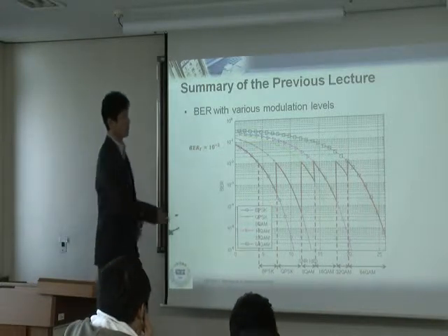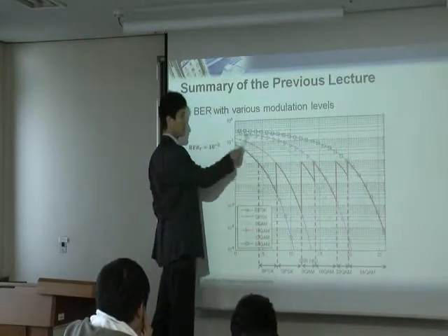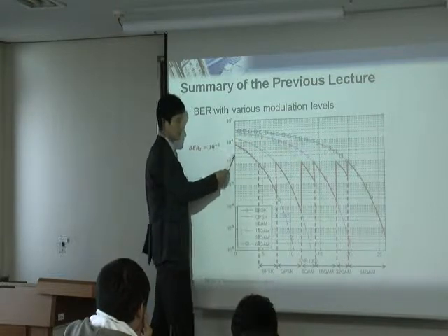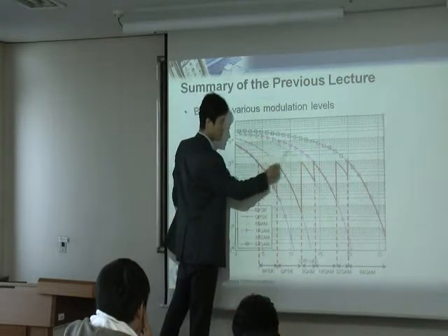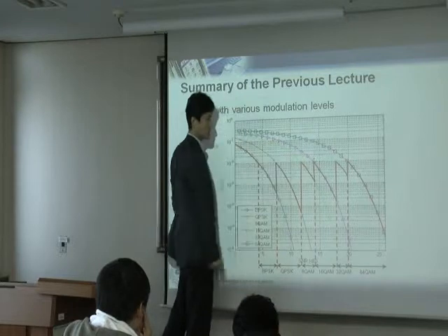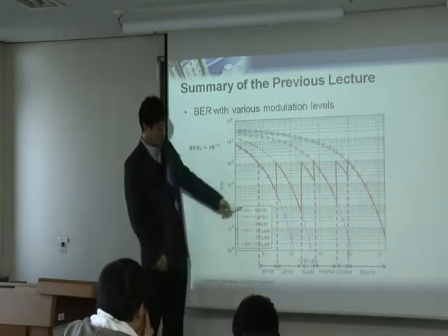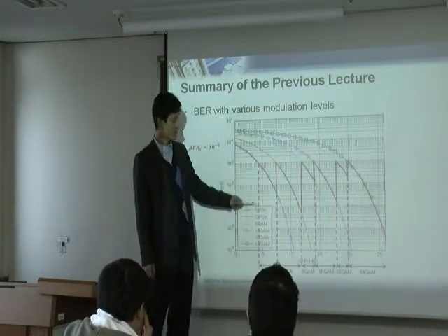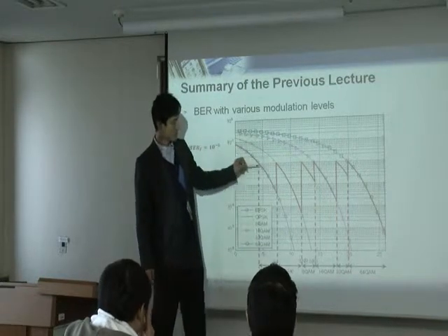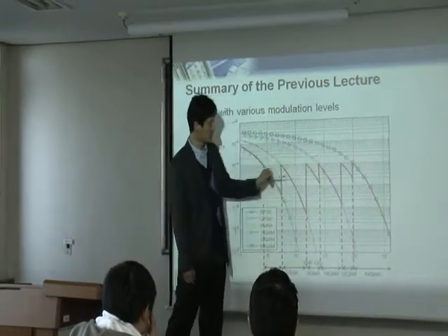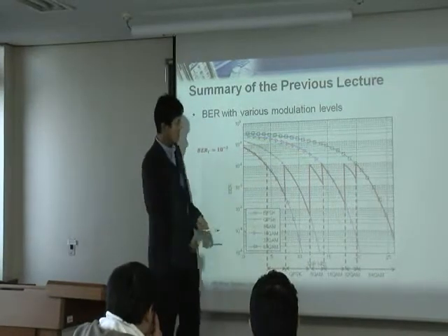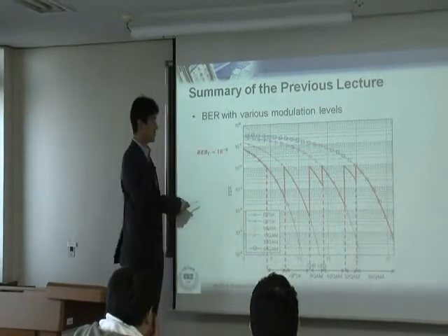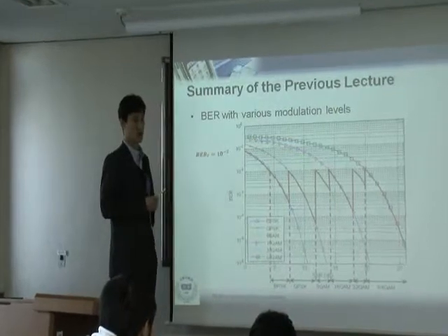To get this threshold, you plot the bit error rate, or actually the symbol error rate, for all the possible modulations. If you're interested, say BPSK, QPSK, all the way to 64 QAM, then you plot the symbol error rate for all these modulations. And then you also have to think about what would be my target bit error rate.